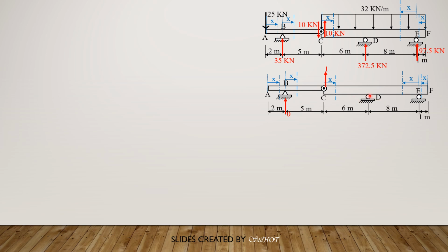Then summation of moment about D, considering this. So this is also 0, just to the left. Then the unit load is just to the right, or even applied at C. So 1 times 6 equals the reaction at E, which is upward, times 8. So it is 0.75. So EI times delta C is equal to, of course, the first term would be 0. The second integral would also be 0.